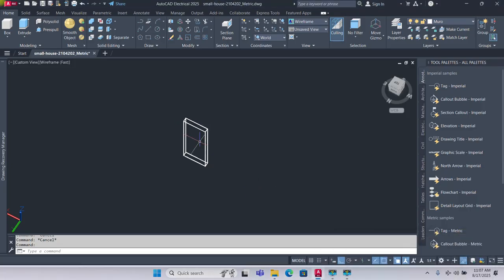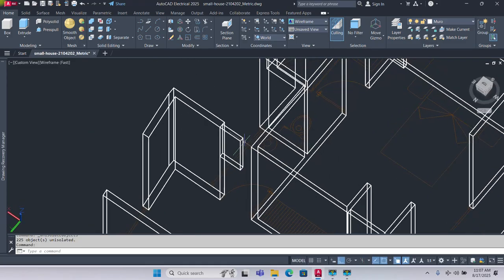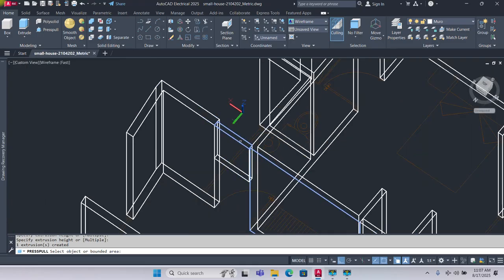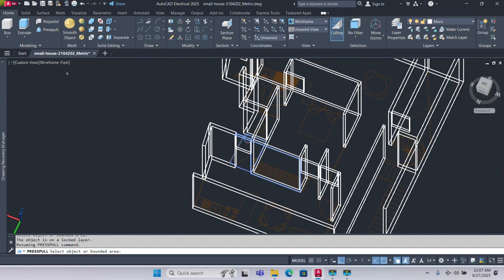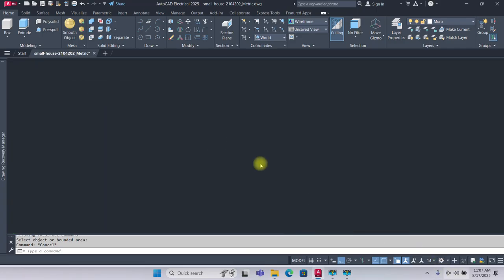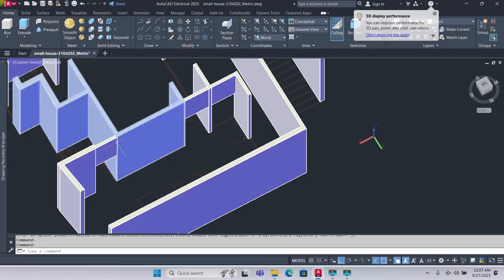All right. Once I'm done, I'll just unisolate. Okay, let me close this first. I'll unisolate by clicking here, and then I'll end object isolation, and then I have this object right there. I just need to now press pull this back to this surface, and that's all I need. So if I run my press pull, select that face, I can come to this face, and that will be on that surface. All right. So you can just use that to build everything, and then you have your door openings and all of this.